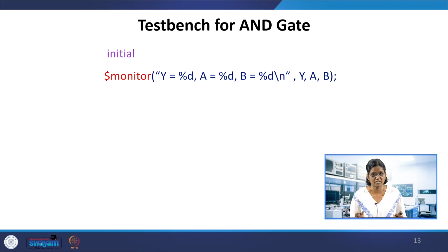In the waveform editor, the design suite has, if you recall, a template generator or text template generator which can give the test bench template also. The text editor allows you to write it, so that, as we write the code for the module, for example this AND gate, the test bench for the AND gate should be written in another .v file. The third part is how we view the changes in the input and the corresponding output. So initial, again it is only one statement. $monitor is the key statement used to observe input changes and the corresponding output.